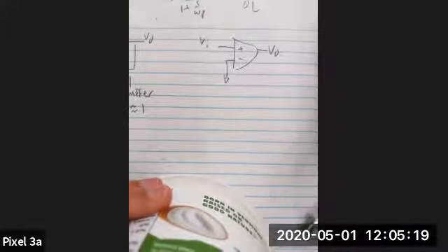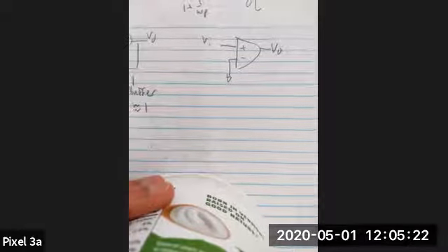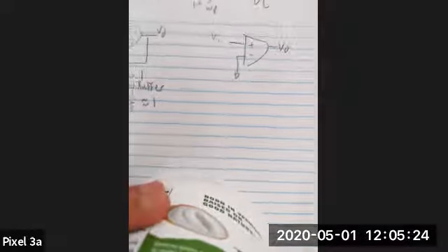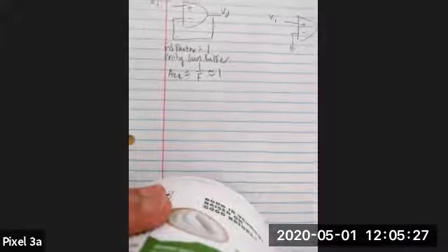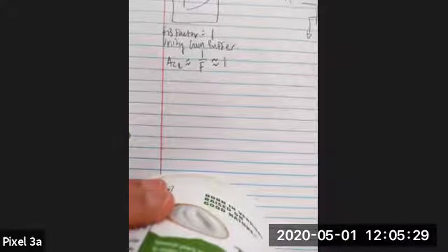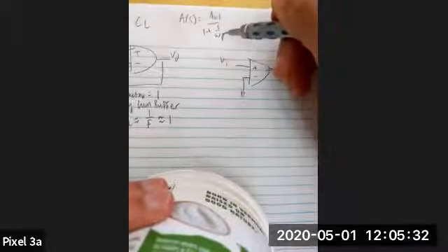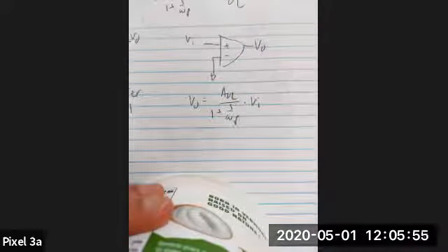And then here we have an open loop configuration, which is just like a standard thing. So if we're going to analyze this in the Laplace domain, which involves usage of these S's, let's first analyze the open loop case. In this case, we have V out is equal to just the gain, which is given over here, times V in, and the minus terminal is grounded, so we don't really worry about that.